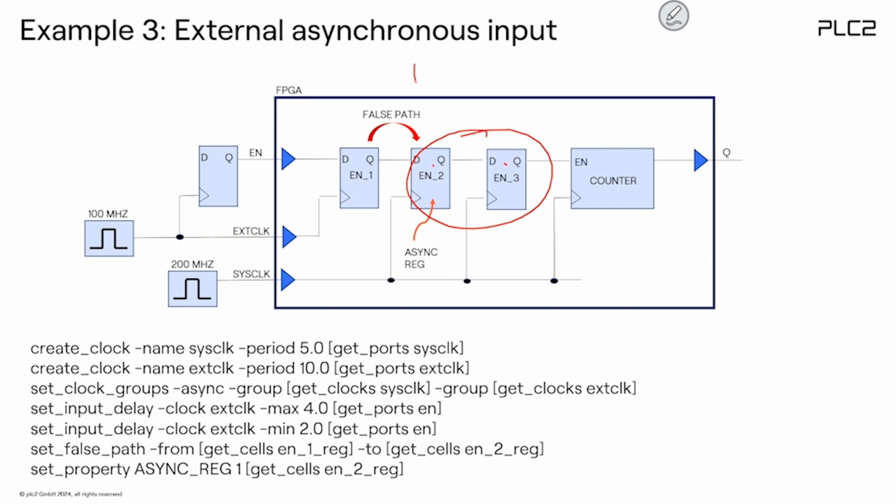Okay, this is a shift register which contains 2 flip-flops. So this is a 2-bit shift register. But there are 2 ways in the AMD FPGAs to implement this register. It could be real flip-flops, or it could be RAMs connected as a shift register. RAMs are not hardened against metastability, they are very bad. Flip-flops are very good for metastability issues.